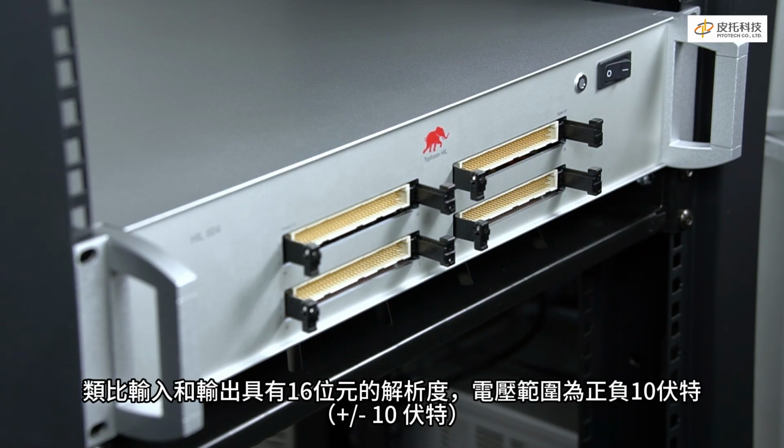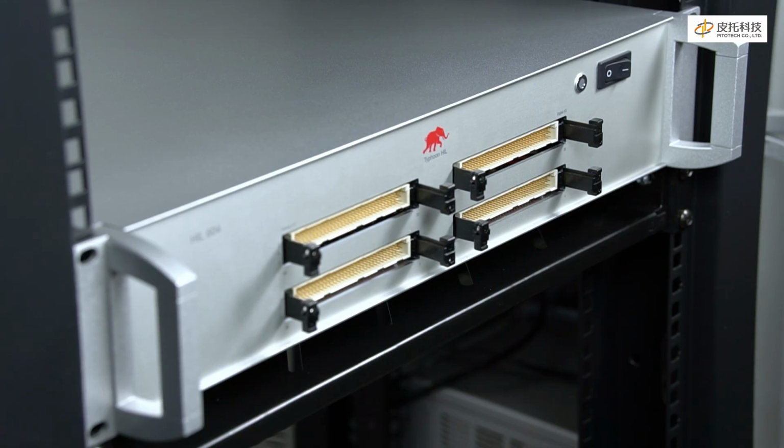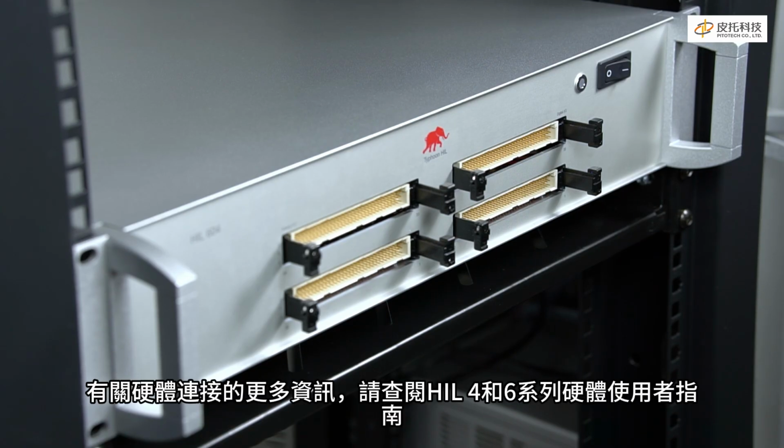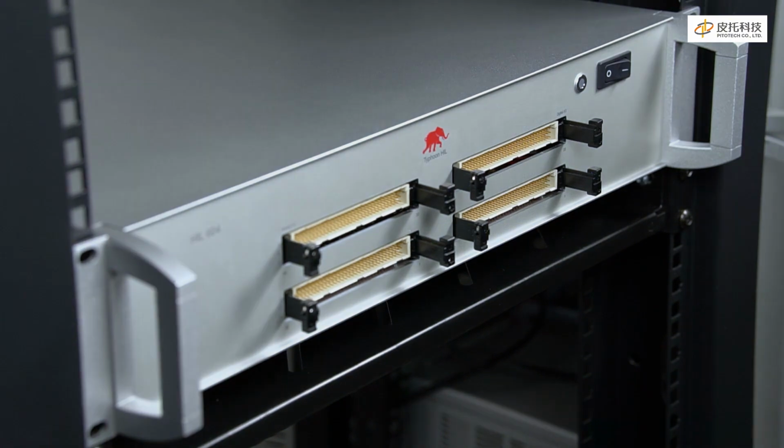Analog inputs and outputs have a resolution of 16 bits with a voltage range of ±10 volts. Digital inputs and outputs are standard 5V CMOS logic I/O, fully protected up to 24 volts. For more information on hardware connections, check out the link to the HIL 6 series hardware user guide. Now that we've finished with the front side of the HIL device, let's move to the back side.